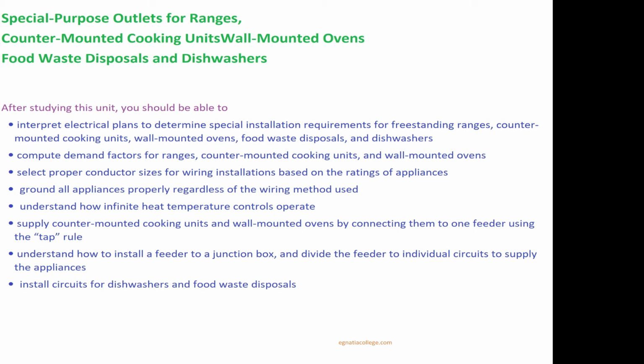Supply counter-mounted cooking units and wall-mounted ovens by connecting them to one feeder using the tap rule. Understand how to install a feeder to a junction box and divide the feeder to individual circuits to supply the appliances. Install circuits for dishwashers and food waste disposals.